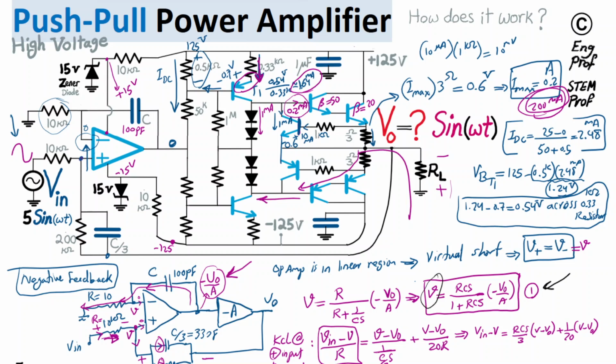So basically this is the operation of the circuit. The current limiter works as soon as the current reaches 0.2 amp, either on the upside or downside, and these diodes support the current sources and make sure that the Darlington transistors are on the verge of turning on, so that the dead zone is avoided. Basically the idea is that output voltage dead zones are avoided.